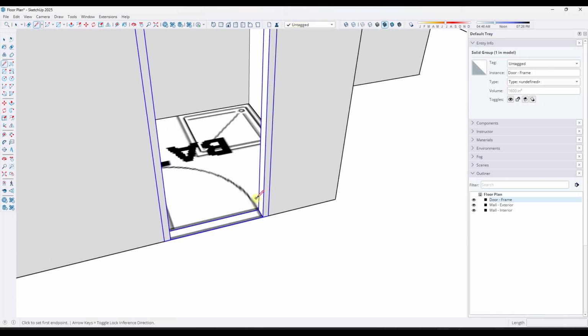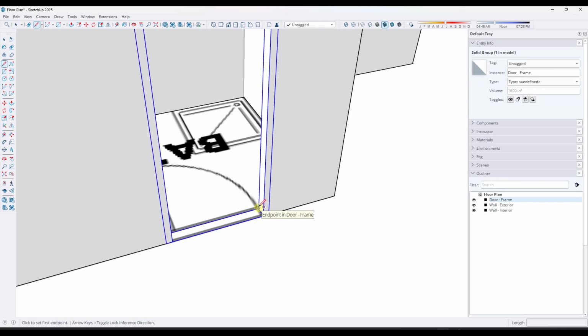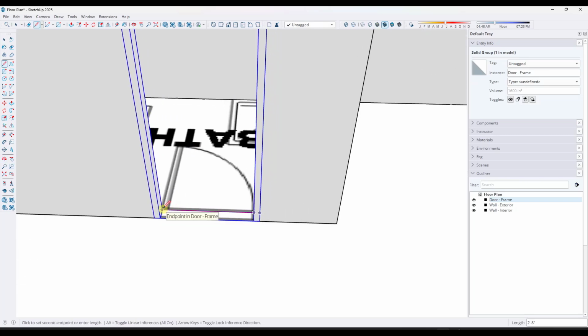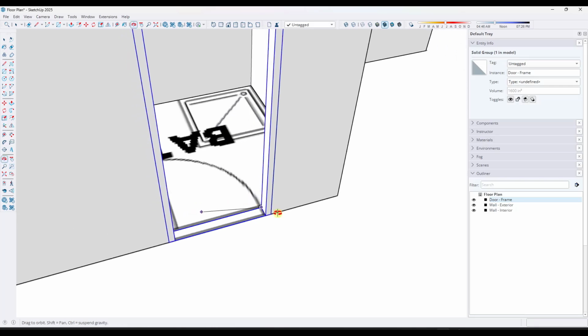And in this case, what we're going to do is start by modeling it flat. For this door to fit in this frame, it would actually have a length of 2 foot 8 inches. Notice how I'm checking that using the line tool right here. Now I'm just going to draw a line that's 2 foot 8 inches right here, and then give it a little bit of thickness. We'll say it's going to be, call it, 1 inch thick.